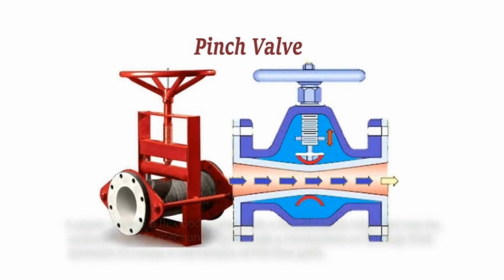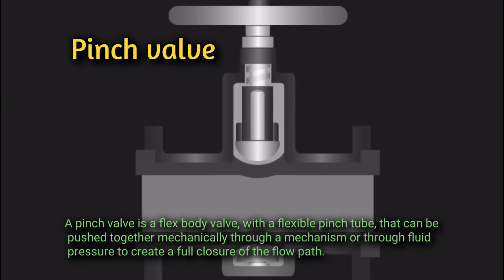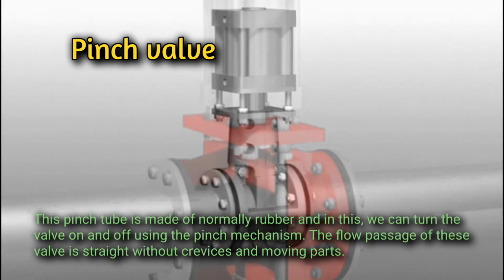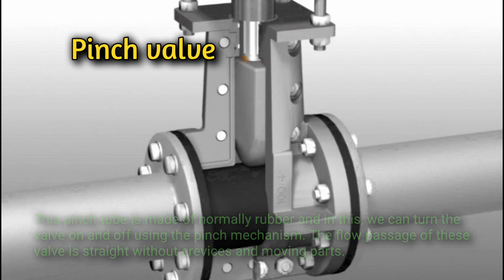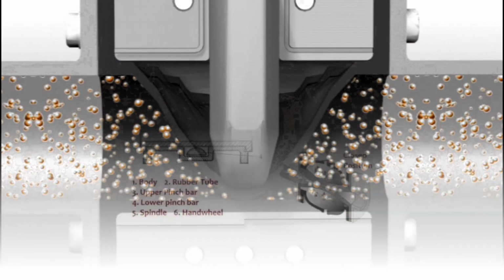Pinch valve. A pinch valve is a flex body valve with a flexible pinch tube that can be pushed together mechanically, through a mechanism or through fluid pressure, to create a full closure of the flow path. This pinch tube is normally made of rubber, and we can turn the valve on and off using the pinch mechanism. The flow passage of these valves is straight, without crevices and moving parts. A pinch valve is ideal for handling slurries, solid materials and liquids with suspended solids.